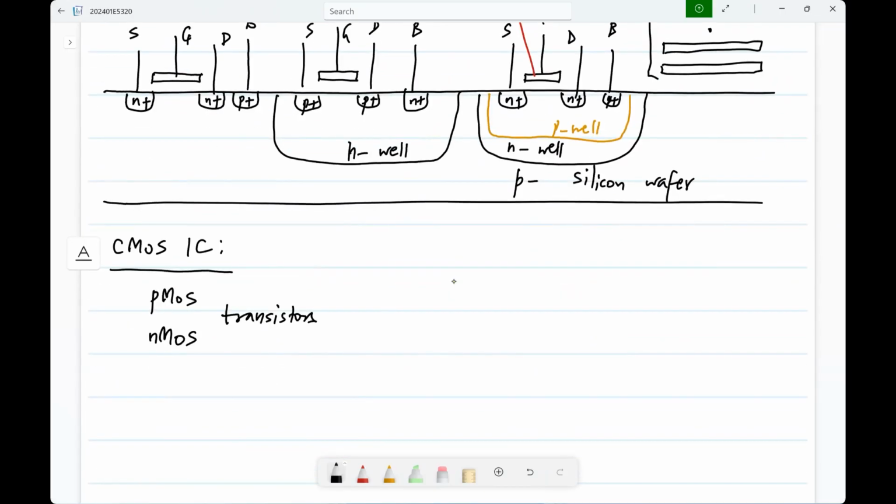And then you can make resistors. Anything that conducts is also a resistance, but of course the resistivity can be different. So it may be convenient for making some values of resistance and not others. You can make these in polysilicon or the metal layers. And you can also use the semiconducting layers, that is any of these N regions, P regions, this N well region and so on. Those also can be used as resistors. Only thing is they will be nonlinear.